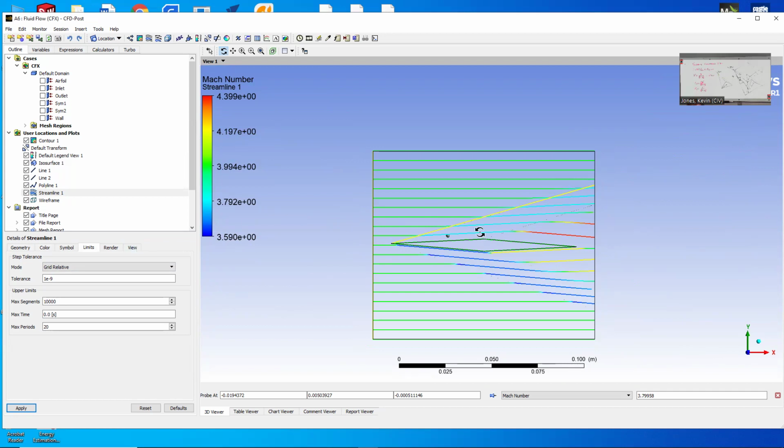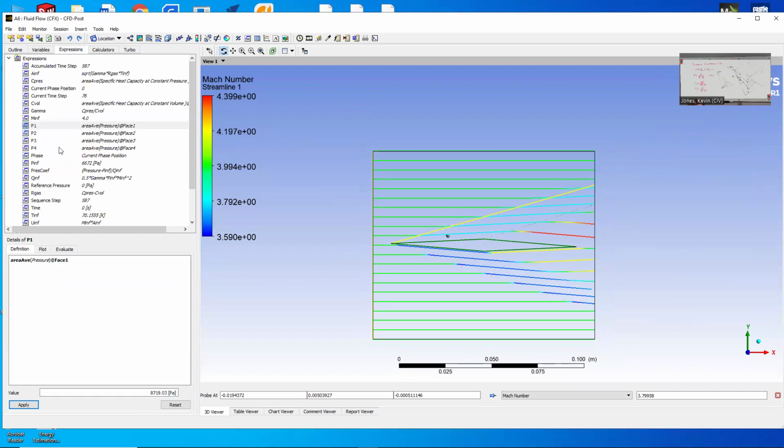You can go in and actually look at the gamma that it gets. We actually have it, it's in the expressions. So what it gets for gamma is 1.40025, so it's close. That one's not the problem. R is a bigger problem. This is off a ways. What is it? 286.9, I think, is what we usually use. So it's off a little bit. You can go back and plug that gamma into the PT calculator, but it'll show up in like a piece of a Pascal with pressure. The shock won't change enough to notice.